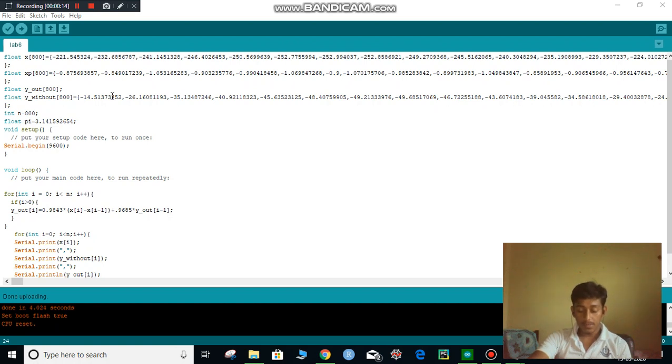So, in this experiment, we need to design a filter to remove the baseline having a frequency below 0.4 Hz, using the pole zero placement method, and implement the algorithm on Arduino using the following signals: one PPG signal without baseline, one with baseline, and one with baseline and 30 Hz power line noise. Here the sampling frequency Fs is 80 Hz.